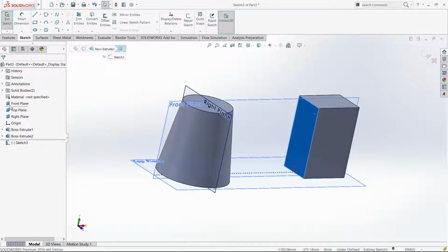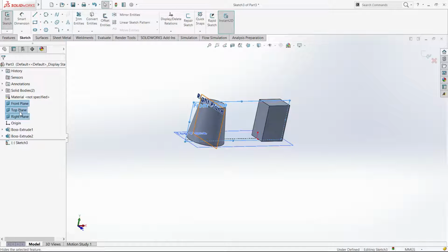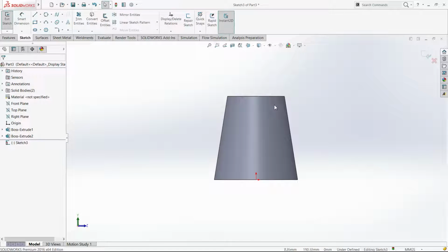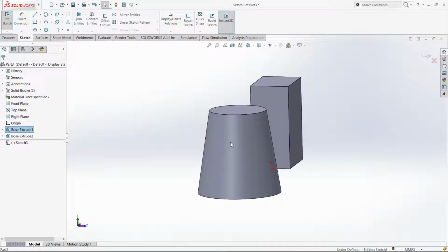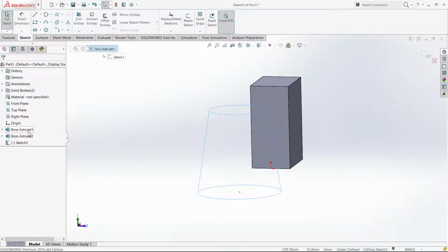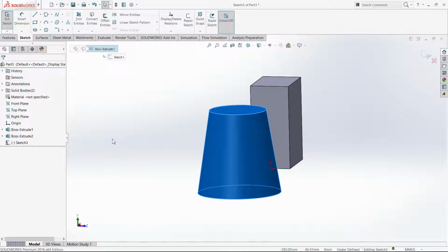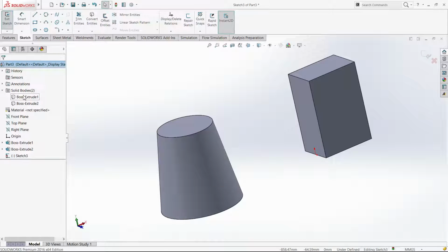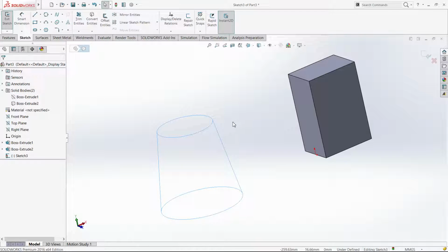So I'm gonna just hide these main planes and go Control 8, and that's gonna allow me to draw on that plane, but we have this solid here, so it's not gonna let me see it. So I can hide this solid or show it, obviously. And since these two are separate bodies, separate solids, you can select each and every one of the solids and hide them, and you see there's no issues there.